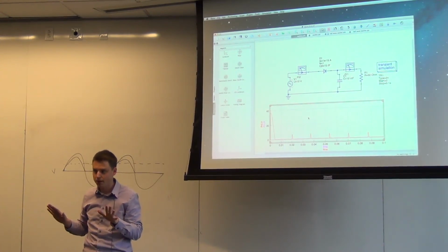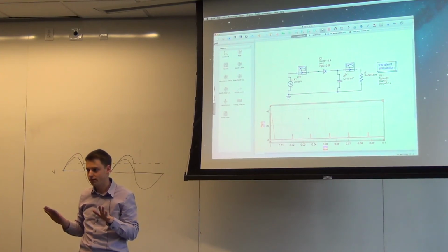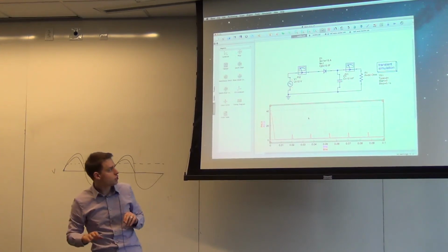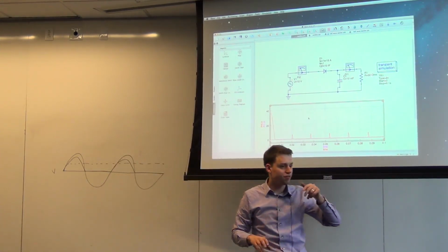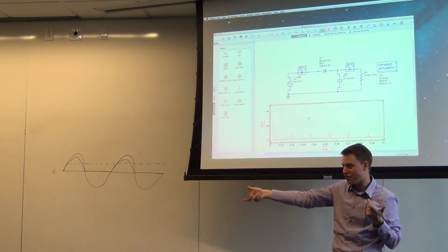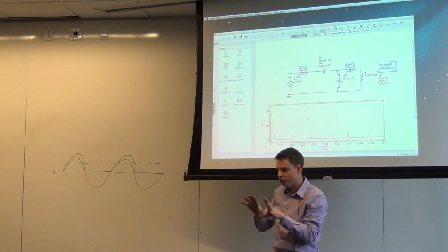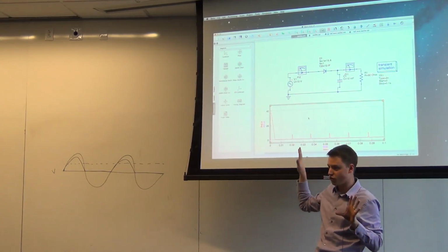What's happening there? How does it demand current? Like, what I mean is, how is that voltage source not just always a 60 Hertz sine wave? Right. So for a voltage source to draw any current, there needs to be a load on the other side. So this is showing current, not voltage. The voltage source is constant, right? So the voltage itself is constant. This is showing the current being drawn from that.